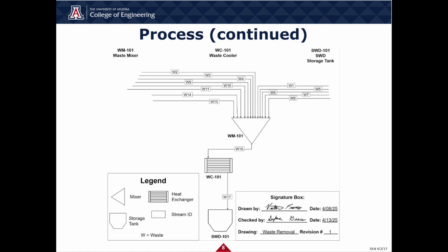Moving into the ethanol recovery and waste removal, this part of the process is identical for both ethanol recovery and waste disposal. However, the only difference being waste is sent to a saltwater injection well, while ethanol is sent back to its storage tank. This is done by combining their respective streams before cooling off to their required temperatures.